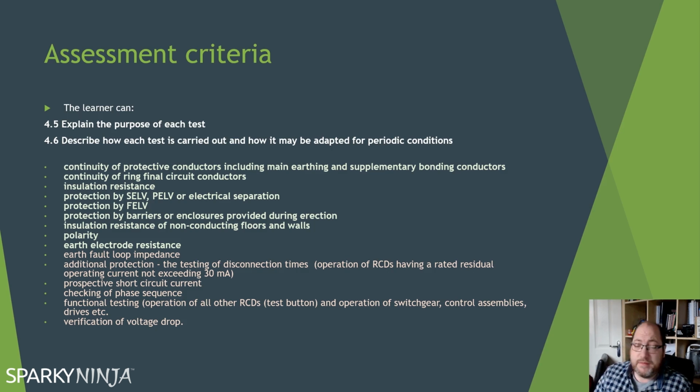Earth electrode resistance, if applicable. Is it for a generator, or is it for a TT system, or is it for an EV charging point, or is it for a TNC system, as we're going to be seeing forward with the 18th edition next year? If it's a dedicated electrode, not on an energized system, it must be an earth electrode resistance tester. If you have a source of supply and you have a suitable RCD in place, you can use an earth fault loop impedance tester to verify it.